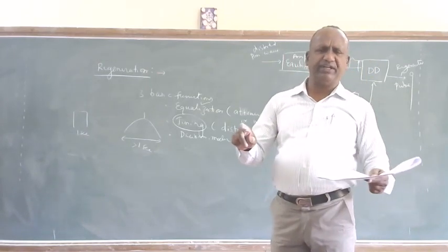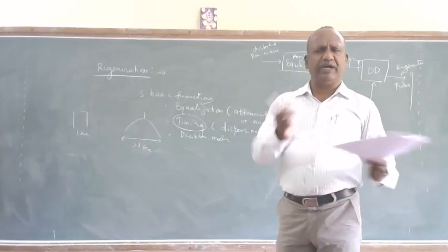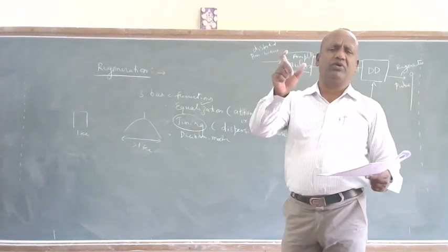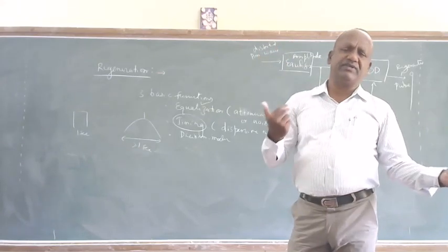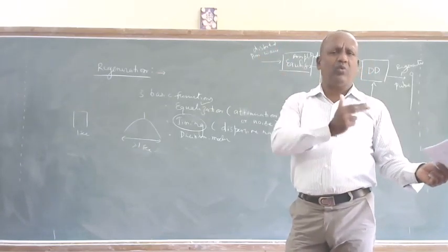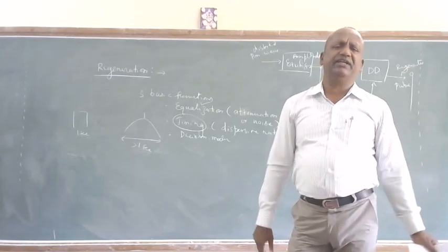I think you know the decoder. Similar to the encoder, you get back to the decoder. I am doing encoding with 8 bits as one code for one level. Then at the receiver side, you use the 8 bits to get back to one quantization level. This is called the decoding operation.